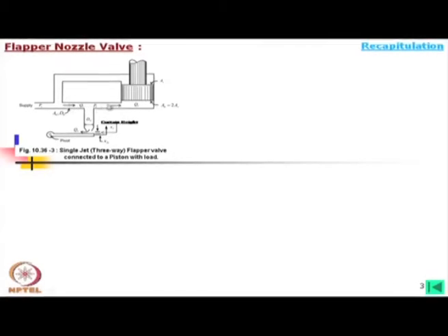first of all it goes through a fixed orifice; here the orifice is fixed. In the case of the spool valve, this orifice is also varying, but in this case this is a fixed orifice and this is being controlled. Another thing in such control is that, instead of this opening, which is circular, the important area is the curtain area.